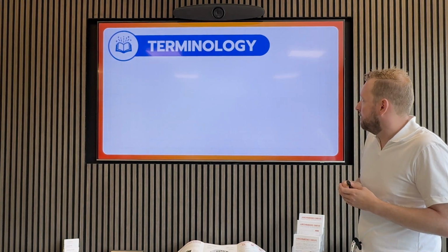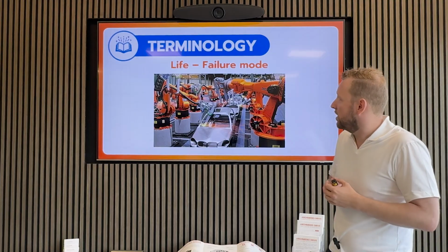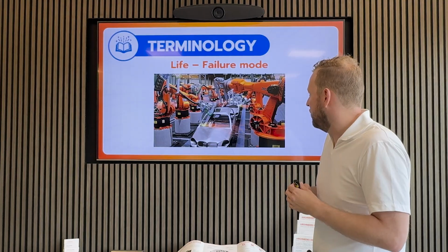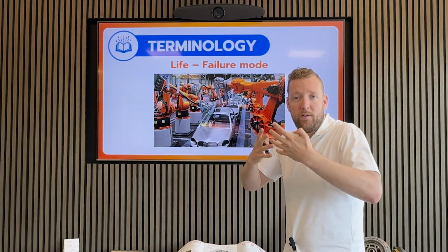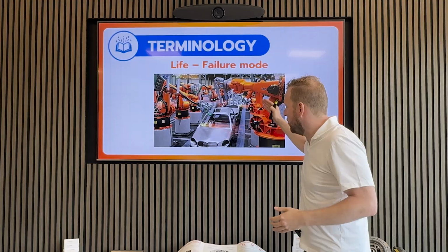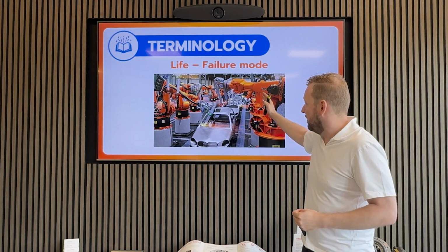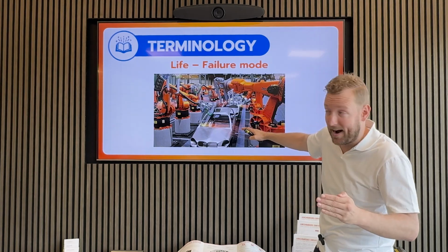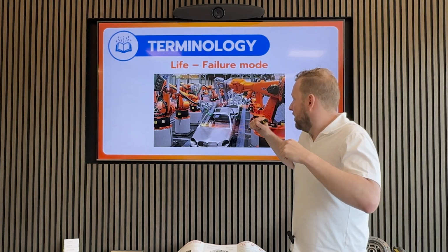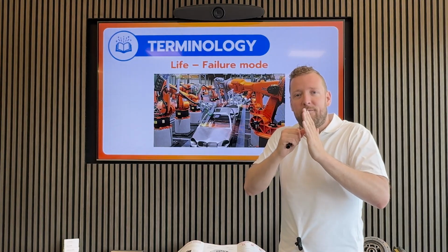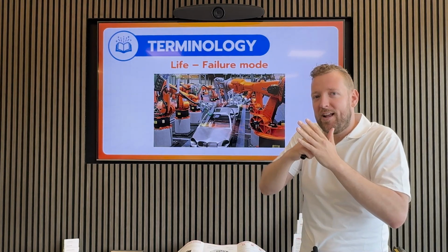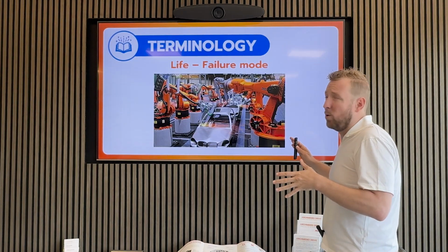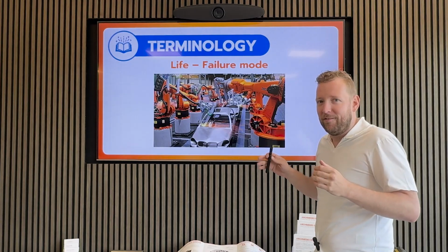But you need to see it also versus the end of life, that failure mode. I already discussed with you guys that if you have at a certain moment metal fatigue and gear teeth breaks, the robot stands still, this line can't completely function, and if this whole line is standing still, then you lose millions a day if it's not repaired. But with traction drives, you will see that the performance degrades, but it's still running, and that you can schedule your maintenance.